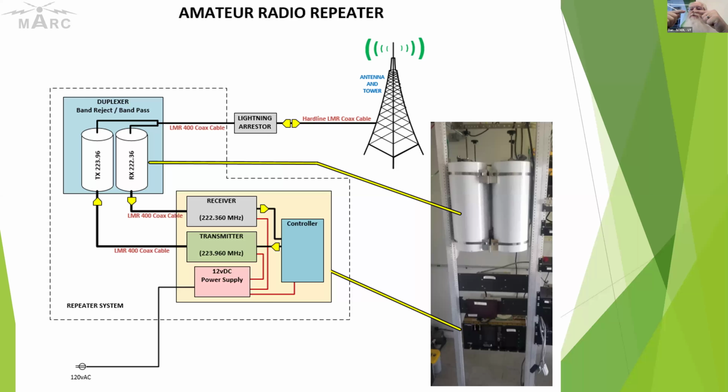Those little gas nodules can be replaced, okay? Now, these aren't for direct lightning strikes, okay? They're for near misses, because 2 million volts on an antenna coax, the antenna is going to lose every time, okay? So it helps prevent that.